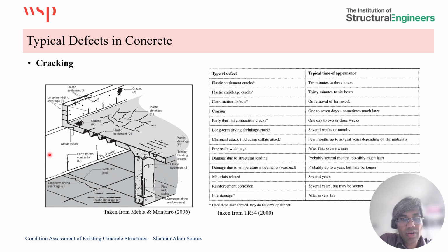So if we consider plastic settlement cracking, or the plastic shrinkage cracking, that can occur just within a few hours of concreting. If we consider reinforcement corrosion, that can occur after several years of exposure, obviously depending on the type of exposure condition and the quality of concrete and reinforcement as well.